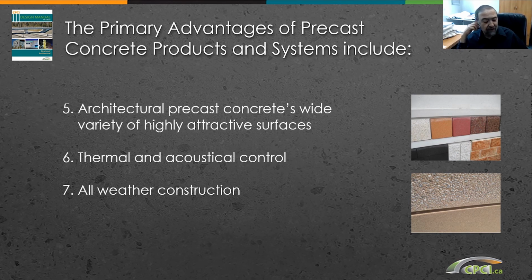Also, I want to add something here that's not on the screen. Prestressing usually decreases the possibility of cracking, by definition, and therefore the cost of maintenance of a building would be reduced immensely if we have prestressed elements. Plant-controlled precast usually gives the architect a huge advantage of fulfilling his dreams of colors and shapes and curves that cannot be achieved by regular cast-in-place concrete.